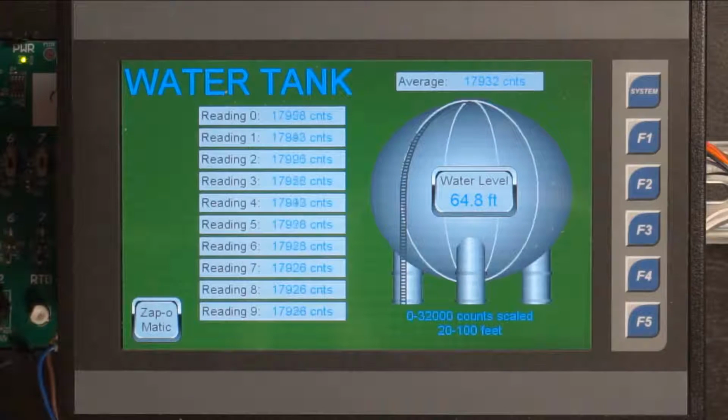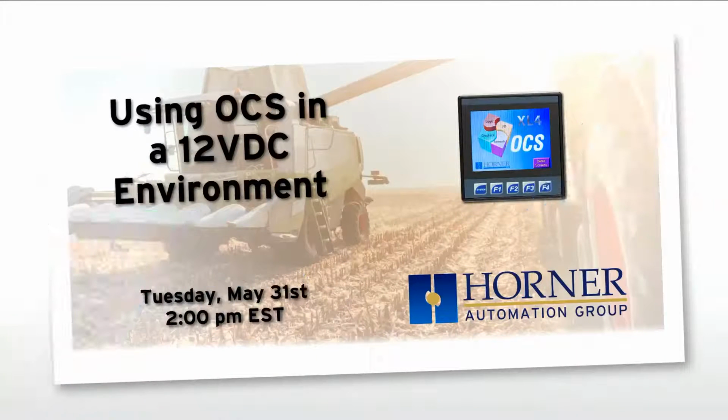So hopefully that gives you another way in which you can use shift registers to store away data that you can then use for some sort of calculation. In this case, just a simple average. Okay, so that wraps up the material I wanted to present to you today. So hopefully those two examples of different ways you can use shift registers have got your juices flowing so you can think about how you're going to use that instruction in the future.